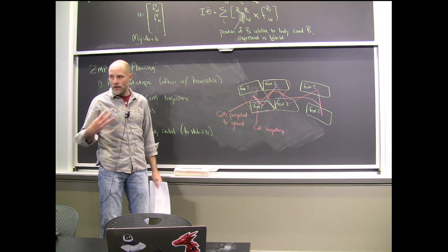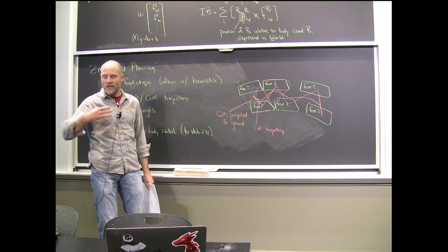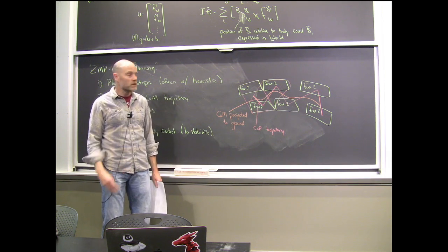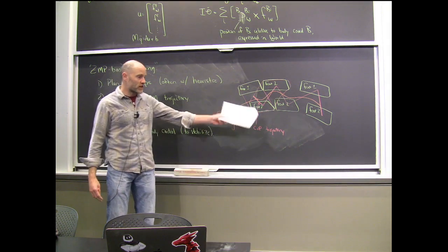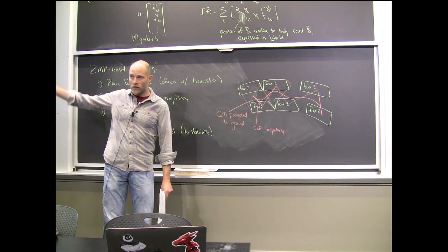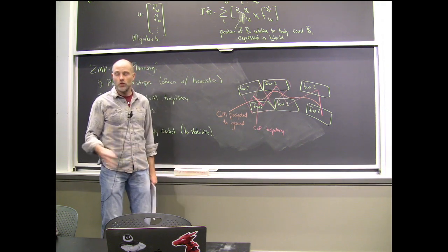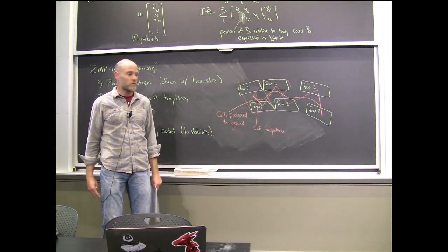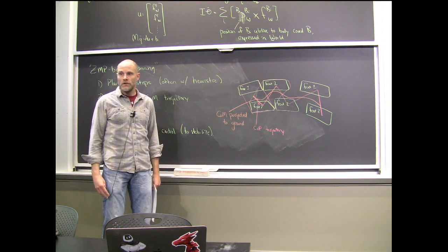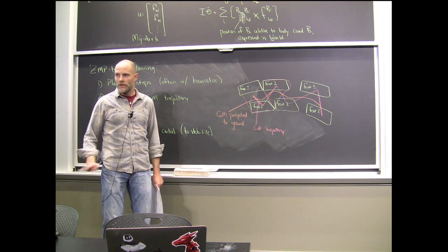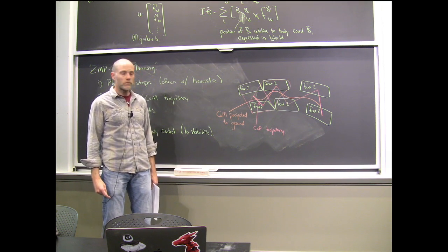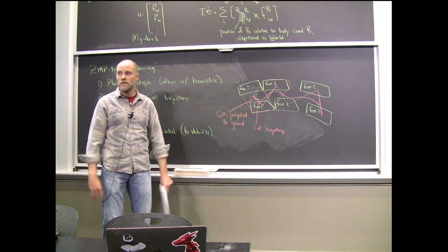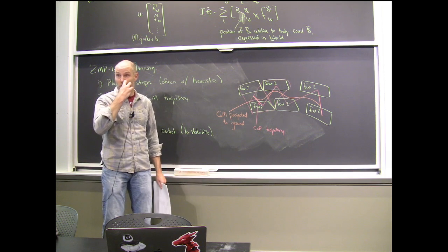The footstep naturally happens once per step. If you want it to be MPC, there's often not a reason to do it more than once per step. The center of mass things can all be very much on the fly, like walking around pedestrians and everything like this. These are all super small, linear MPC problems, even if you put some of the richer constraints in them. So this is very much run on the fly, in real time. If you're picking your way over terrain, it gets more interesting, but that's at the footstep planning level typically.